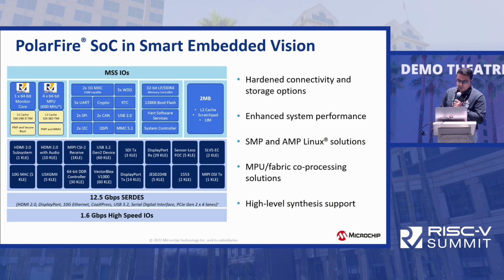In the context of this presentation, I'm particularly focusing on embedded imaging and video applications, including AI/ML. Essentially, what you have with an SoC FPGA is an extremely capable microprocessor subsystem that can be extended beyond its capabilities using the FPGA fabric. So you want an HDMI interface? Yeah, we have it in our soft IP portfolio. You can put it on the fabric and extend the functionality. You want an LVDS interface, or, I don't know, a 10 gig Ethernet interface, name it, and you can get it ported on our fabric and extend the functionality.